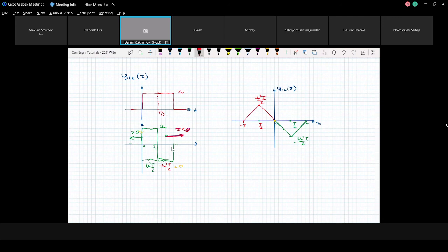And you see that when these two signals are synchronized, they don't correlate with each other. Cross-correlation equals 0. Very often you use this property in CDMA systems because you transmit different sequences at the same time, but because they don't correlate with each other, they don't produce mutual interference.